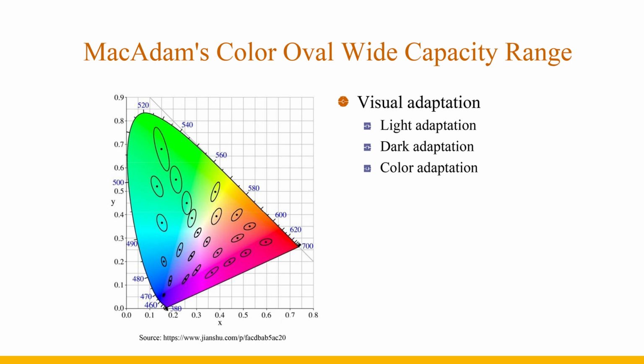In the light environment design, the color quality of the lighting source has a great influence on the light environment, which can change the color of the illuminated object. The reason for the change is that the spectral power distribution of the light source changes, resulting in different spectral power distributions of the reflected light of the illuminated object. This in turn changes the stimulus values, resulting in changes in color perception.